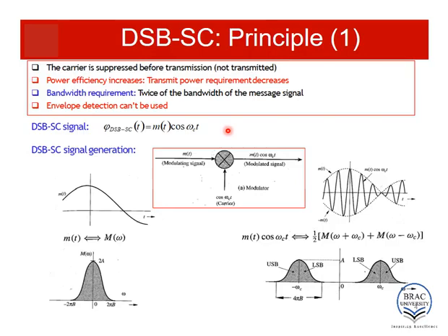So how can we produce this DSB-SC signal? The first approach is very straightforward. As you can see from the equation, this is simply the multiplication of the message and the carrier, right? So we can use a multiplier block, and the two inputs will be the modulating signal m(t) and the carrier signal cos omega_c t. As you can see, there is no carrier amplitude here. That means the amplitude is by default 1. If you use any other amplitude, that is not a problem. The structure will be similar. So this is our modulated signal m(t) cos omega_c t.